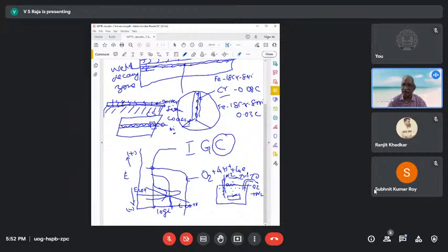But now there are also standalone conversion coatings. What are standalone conversion coatings? The standalone conversion coatings are the manganese coatings, right? You have a manganese phosphate coating. In this case, you are also adding manganese, and you also put some kind of epoxy resin. So they put epoxy resin plus manganese phosphate, and they give you a coating. The conversion coating is a really good coating. It's a combination of conversion coating plus your epoxy.